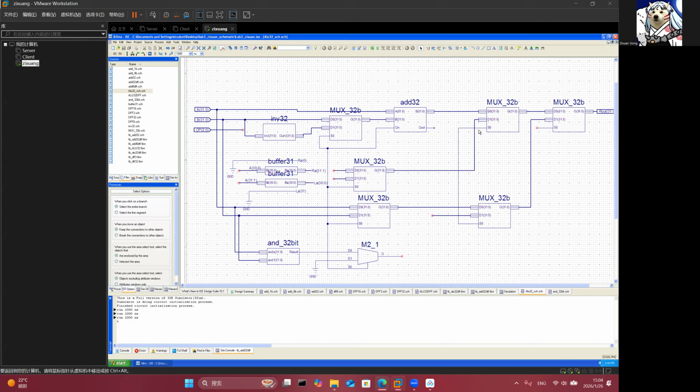And then I used the OP1 to control if this mux output is either copy or shift, or if this mux output is the equal or the default case. And then the mux is controlled by the OP2, the third bit of OP, sorry, MSB. And then we will get the output. This is the structure of my ALU.